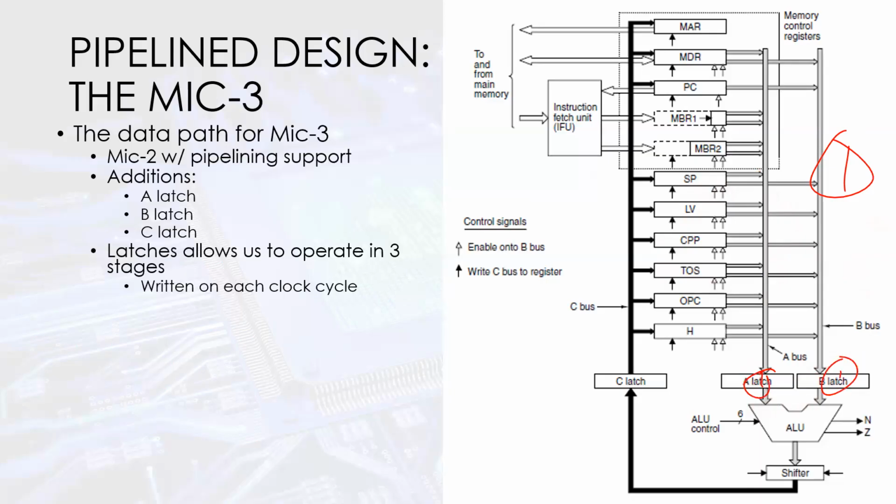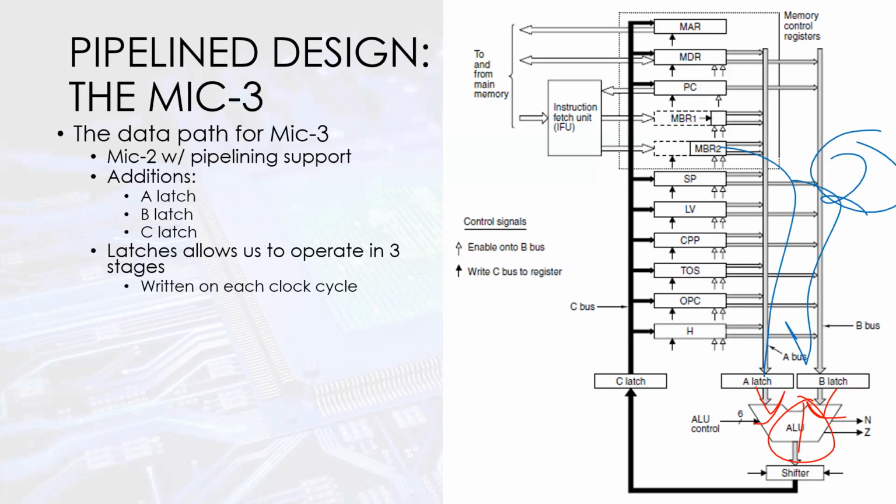As soon as I start the next cycle, that data is no longer just being saved in the latch, but is now down here in my ALU, coming out of the latch, which means I can now have the data coming down for instruction 2.